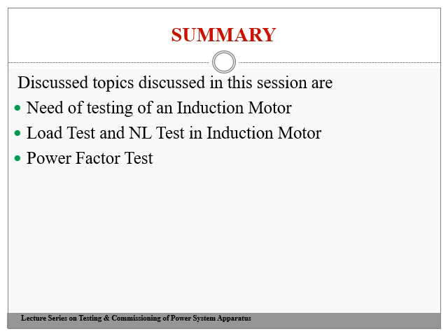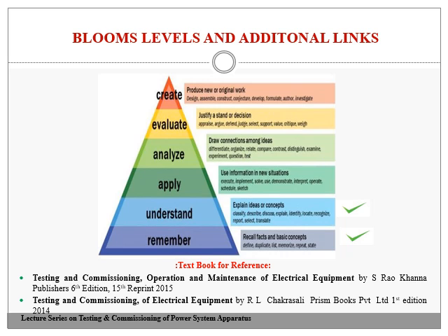Then afterwards we came to know how you can conduct the load test to determine the efficiency, torque as well as the power factor. Then we came to know about the no load test, which is also called the rated voltage test, which helps us find out the no load current as well as the core losses that exist in an induction motor. That is the no load test. All these topics come under the levels of L1 and L2, that is, remembering and understanding.